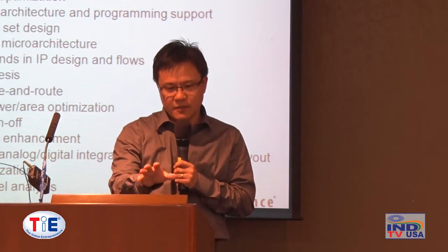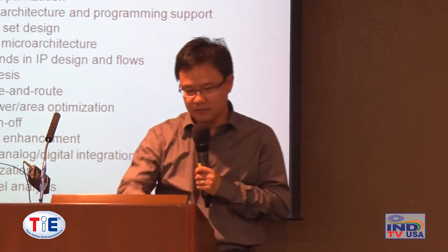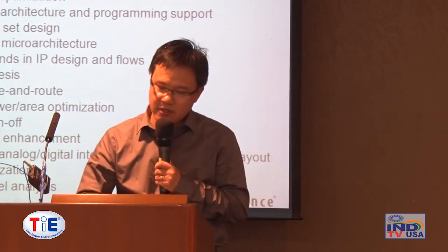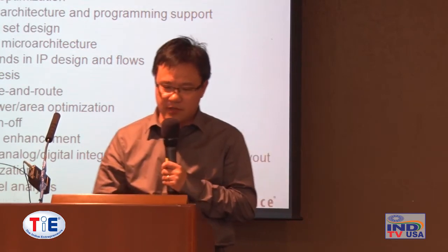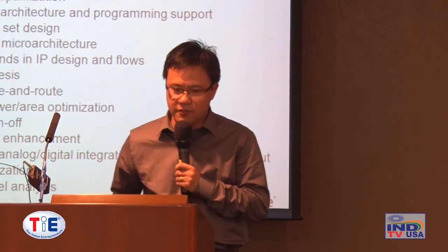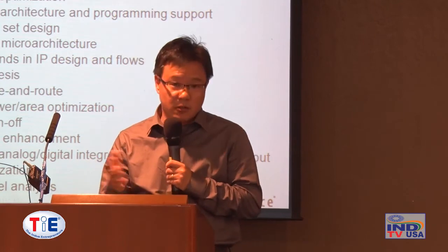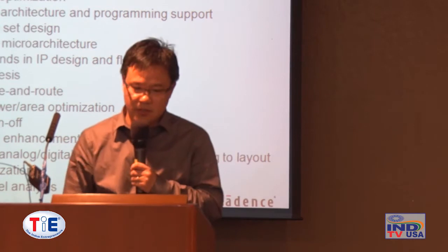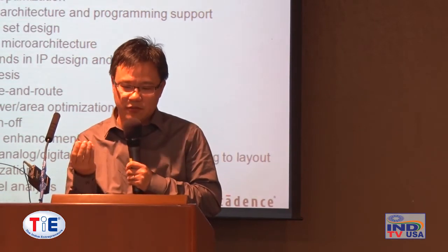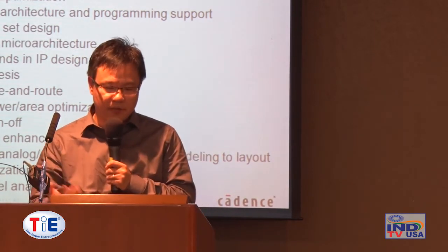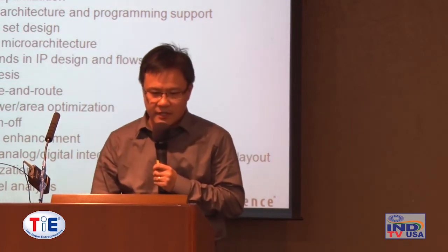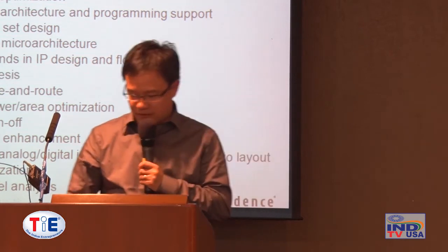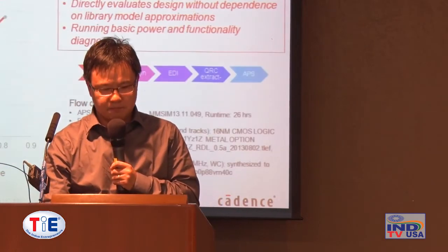That's a little bit of a dive down to say what you're going to have in order to do that. There are a lot of technical details here, but at a high level, you need to define your system architecture. You need software that works with the process configuration. You need digital and analog co-design. You need heterogeneous integration to have sensors, MEMS, and power management chips in a single package to lower the cost. And of course, you have system software integrated together. And these are the elements that, put together, are able to do the SoC for the IoT.